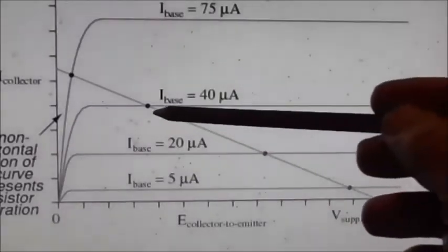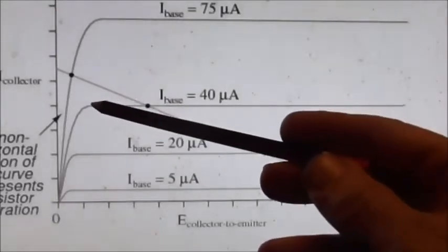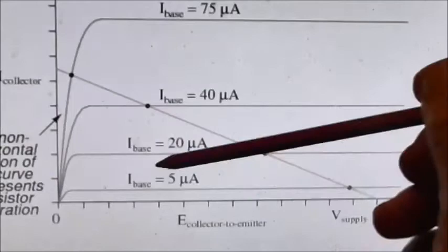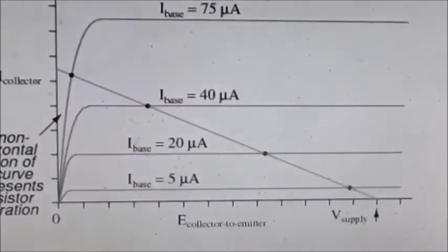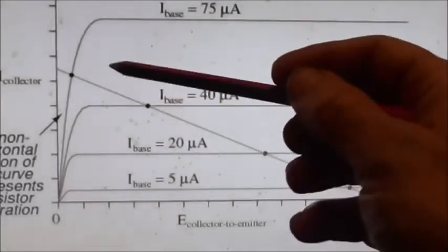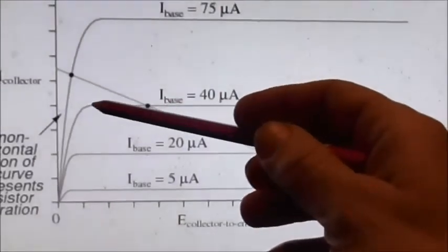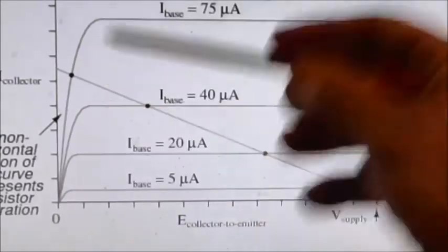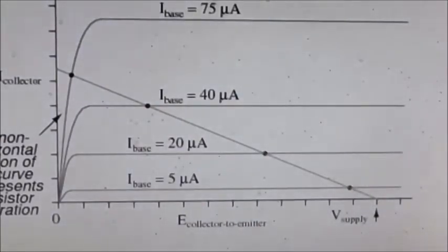When we're making a switch, what we want to do is put it so that it's achieved saturation above the knee. What this does is it keeps the switch conservative. It doesn't allow, even if the voltage drops a little bit, for the current to go up and down, which may cause a dropout at the buzzer.